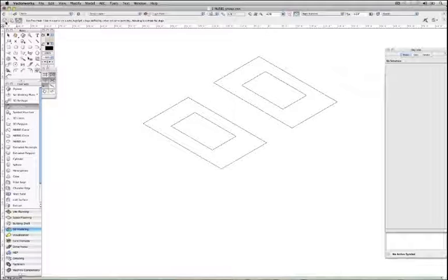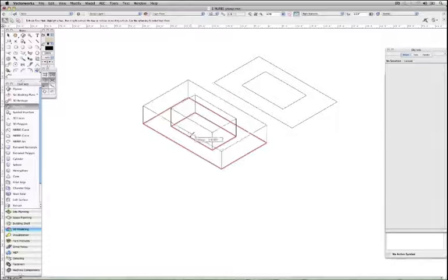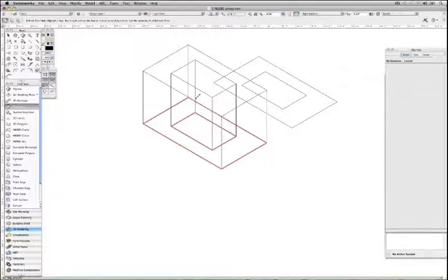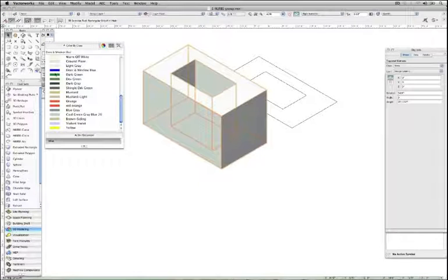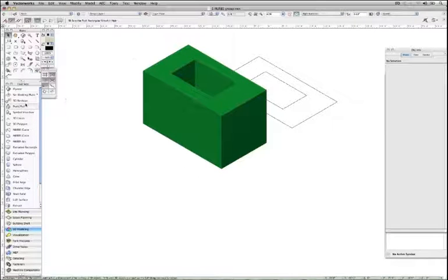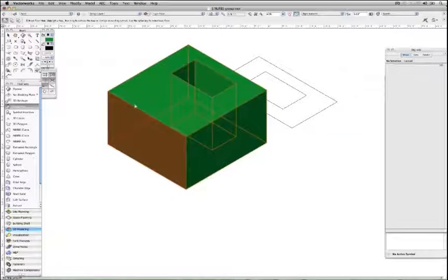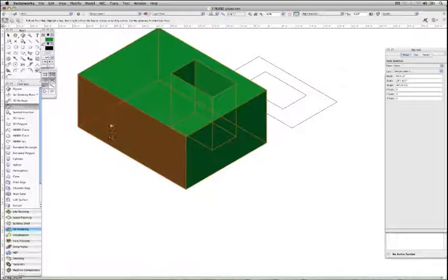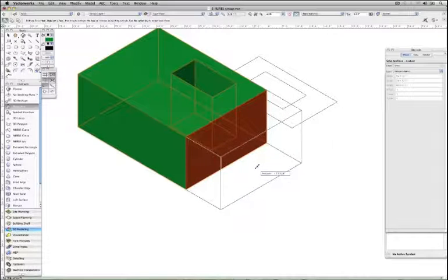As I mouse over the 2 rectangles that are in a group, as you can see, nothing happens. But when I go over to the 2 group NURBS curves, we'll be able to perform an operation. As you can see, I'll give that object some color so you can see a little better. I can then proceed to push and pull on the grouped NURBS surfaces. Another tip here is to hold down the Option key if you need to pick the surfaces that are not up front. This allows Vectorworks to see those surfaces on the back side of your geometry.